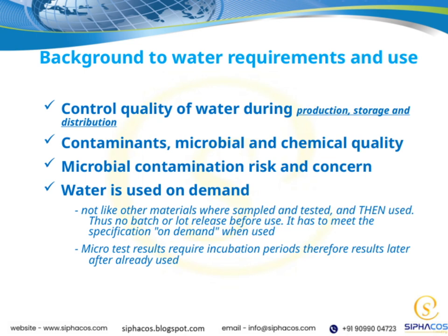This means we don't have the luxury of sampling, testing, and then releasing it for use like we do with other raw materials. Instead, water must meet the specifications right at the moment of use. Microbial test results usually require incubation periods, which means the results come back only after the water has already been used.